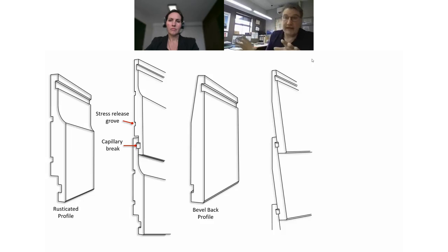That being said, you can get more stable timbers, and Abodo can talk to you about that, etc. But remember, today's just generic. And there are reasons for these different designs, but my favorite is the bevel back. It's very, very simple indeed. And then don't forget, it's a single nail per board.